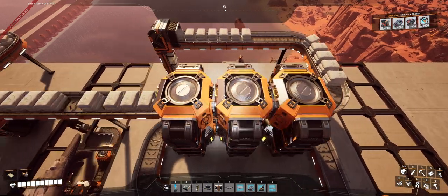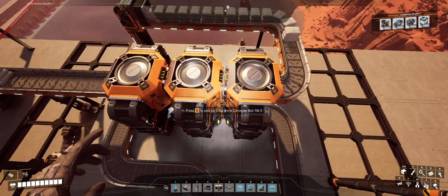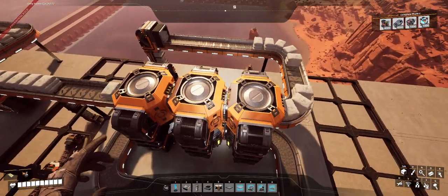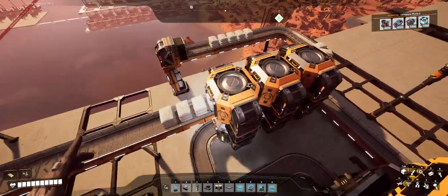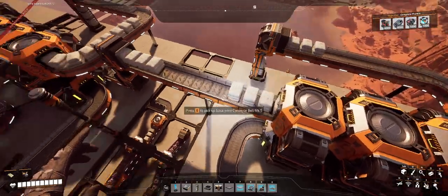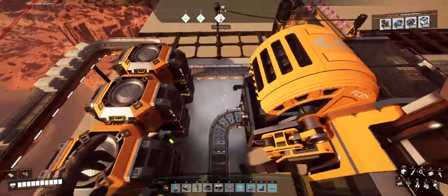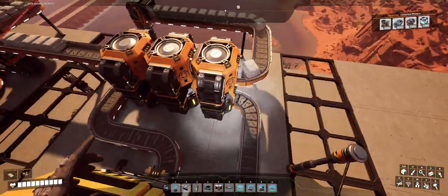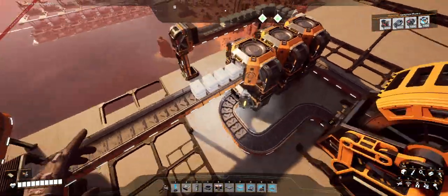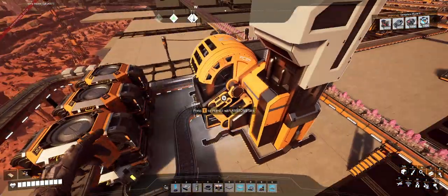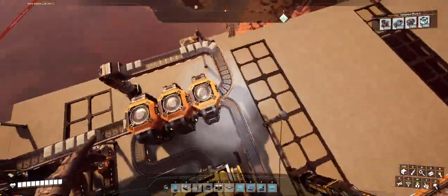Anyway, the reason why I used 3 was, first of all, I didn't do the math at all. I just said, well, this guy's going to be 1/3 from the top and 2/3 from the bottom, so I'll just do it 3 times, and the bottom will have a 27th. But anyway, if the output backs up, which we need to handle, what happens to the bottom? Well, the bottom, we've got stuff coming in, it gets split, and it can't send any up, and it gets split, can't send any up, gets split, can't send any up, and the overflow goes into the sink. So we will never back up this belt.